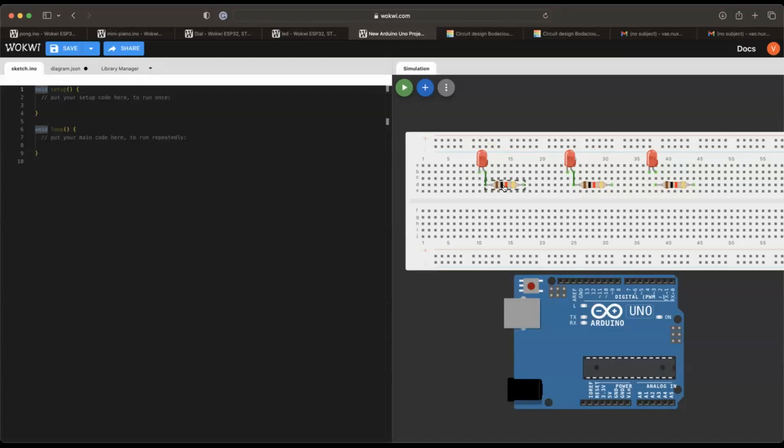R1:1. So how a breadboard works is that under these prongs, there's five pins. On these five pins, they're all connected to each other. On the bottom, there's a metal strip under the breadboard that makes all of these five pins connected to each other.